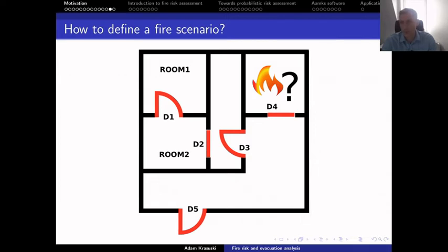We also have fractional effective dose, which allows us to evaluate the consequences of contact of people with smoke. So with these approaches, we may have a very good estimation of what may happen within a defined fire scenario.